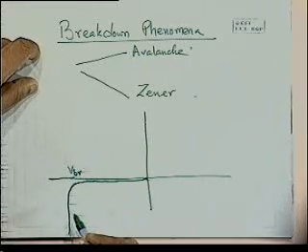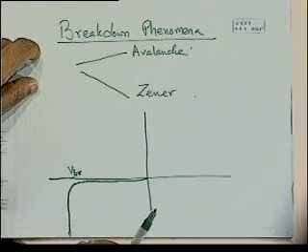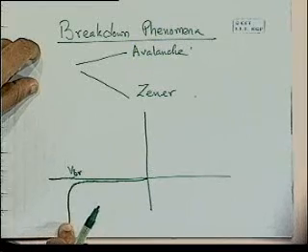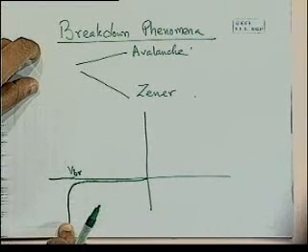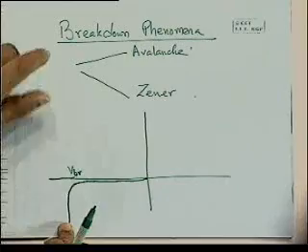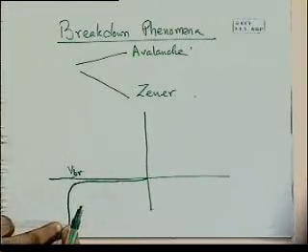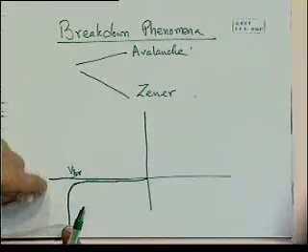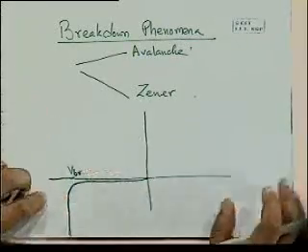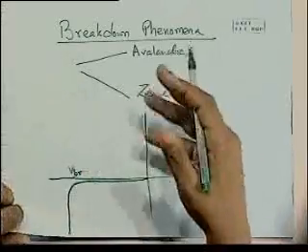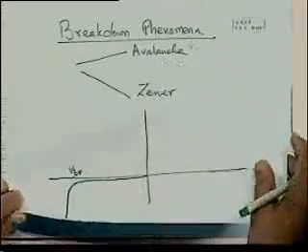And this is made use of in voltage clamping circuits, where you can limit the current by an external resistor so that the current doesn't increase beyond a breakdown point, beyond some burnout point, but you're able to clamp the voltage. It does not go anywhere much beyond VBR, more or less stays in the VBR range. So this is a practical application that you can make use of even with breakdown phenomena where things are falling apart.